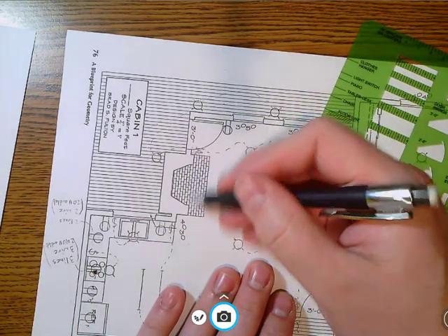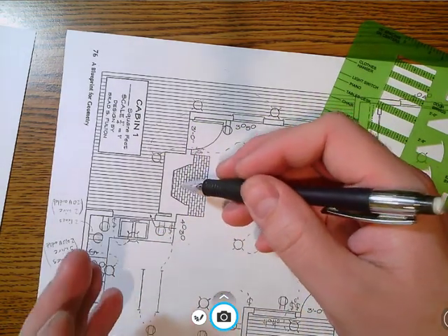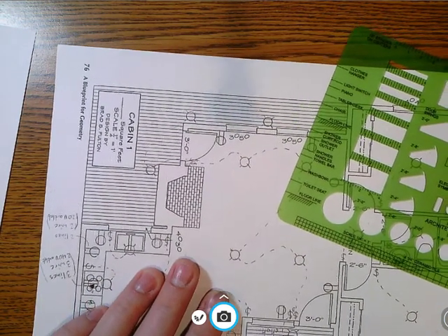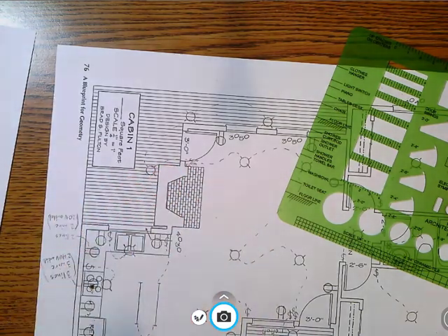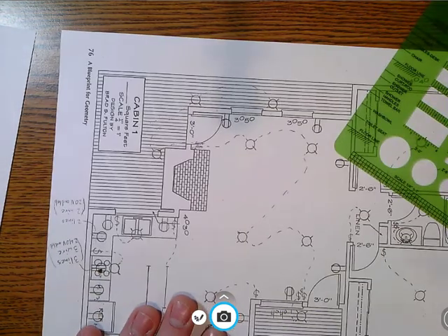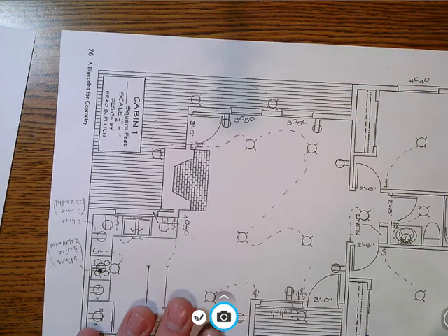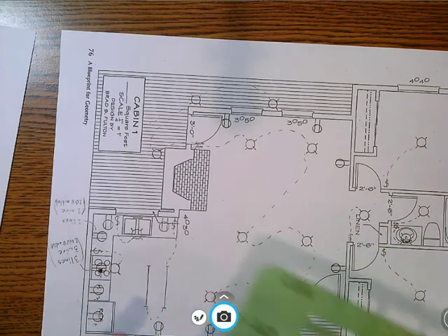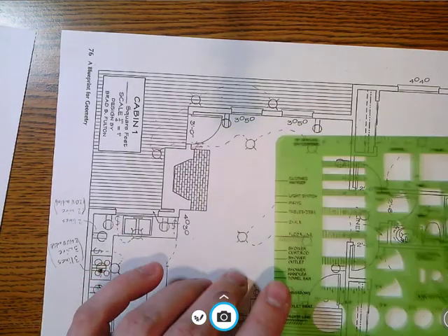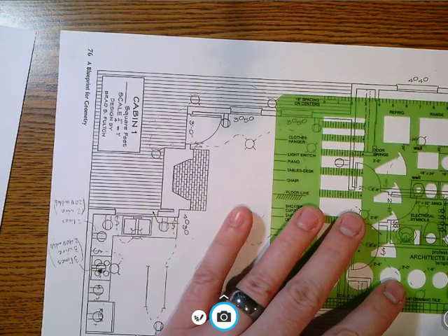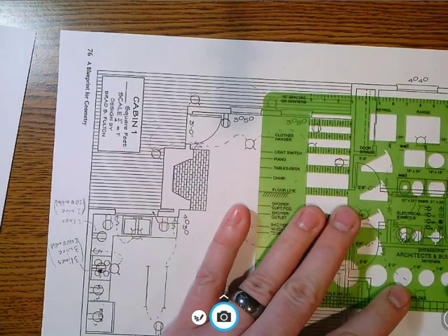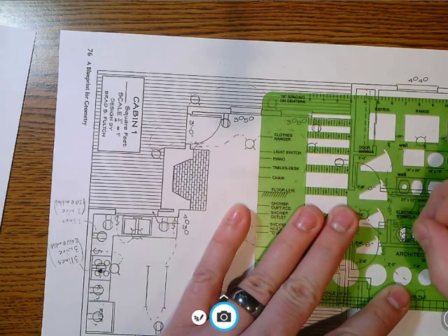And now the chimney here, you could say, oh, that's more than 6 feet of wall space, but you can't really put an outlet in a chimney. There's definitely some safety concerns there. So that is really all we need in terms of outlets and where they are being placed. Now, these walls are shorter than 2 feet, so we don't need an outlet there. Let's put an outlet in the bathroom here, by this sink, for a setup for the blow dryers and such.